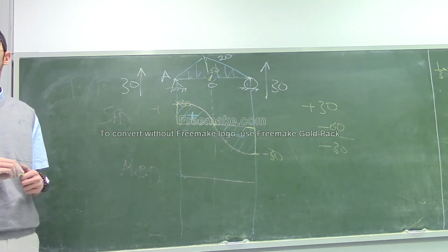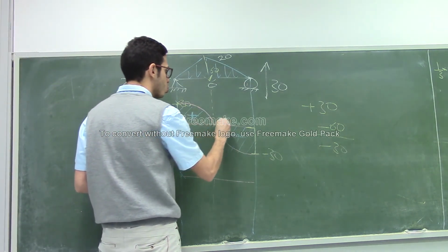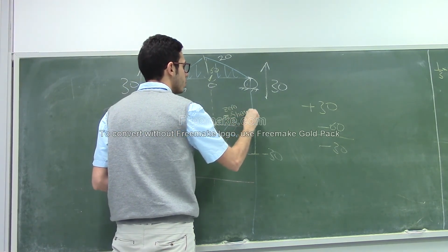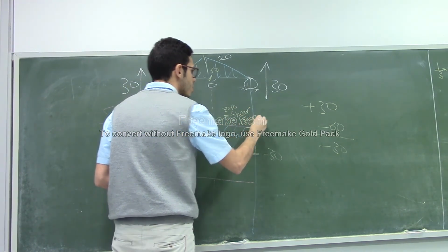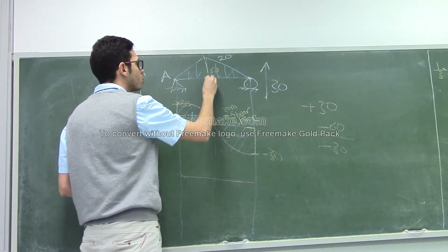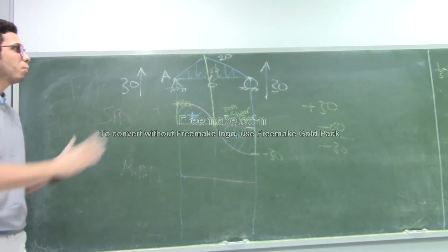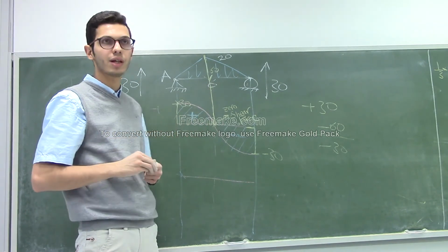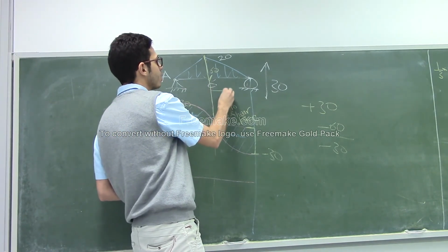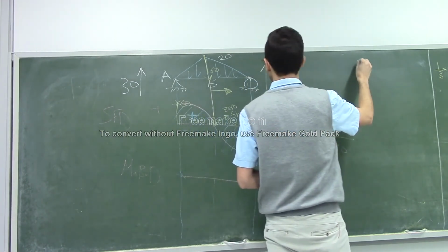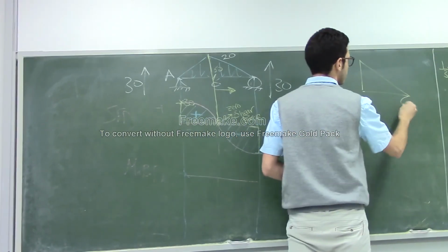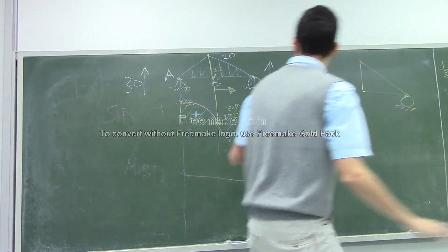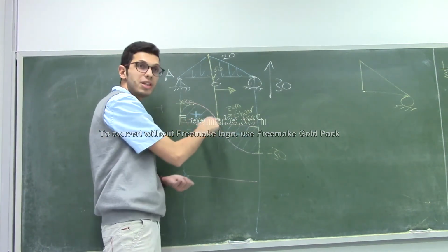it's a 0 shear force, right? Because the shear diagram is 0. So it's a 0 shear force. So if you go back up to the diagram and make a cut, both of them, if you take this side or this side, it's okay. Both of them are triangles, right? So for example, let's take the right side. So the right side is like this.